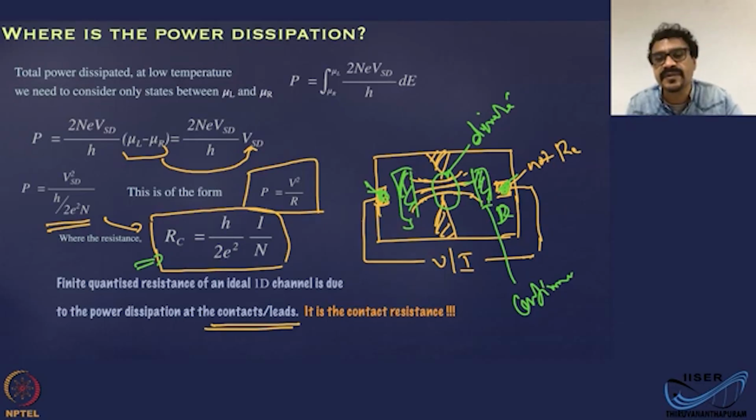So the contact resistance RC, which is basically the quantized resistance that we have derived for the channel, refers to the immediate region where the one-dimensional modes meet the two-dimensional system. That is the summary, or nutshell, of the discussion.